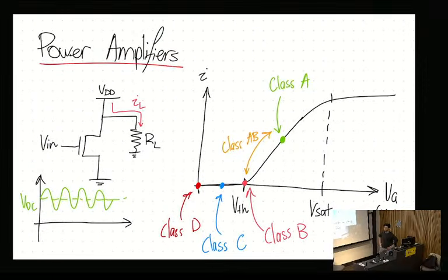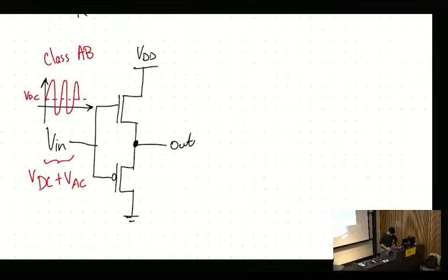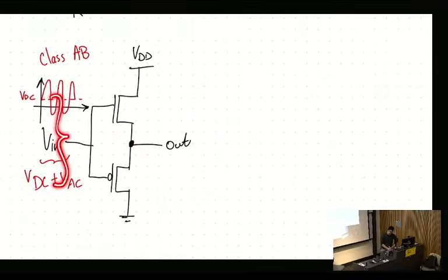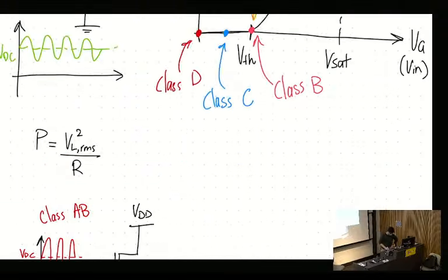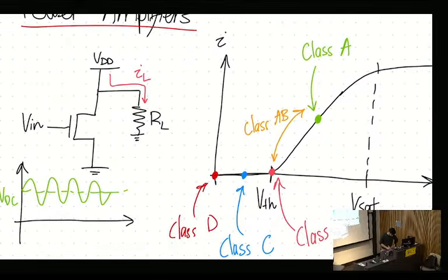This part's a bit hard to explain without the math, because what you actually put here is a VBE multiplier to bias the gate with a particular voltage. When you run through the math, you see that the swing voltage is a lot larger when you bias it in this configuration. But at a high level, it's because in this case we're always amplifying a positive signal.